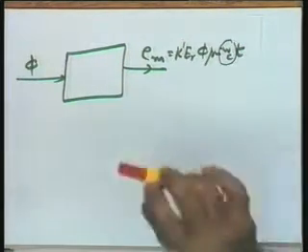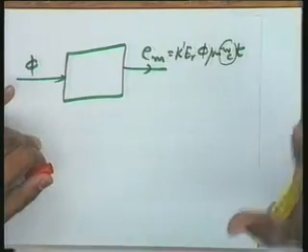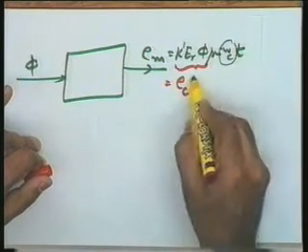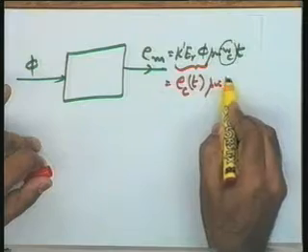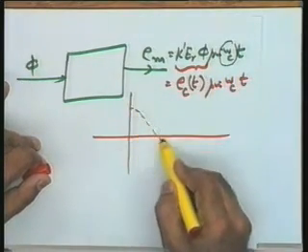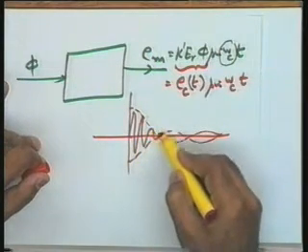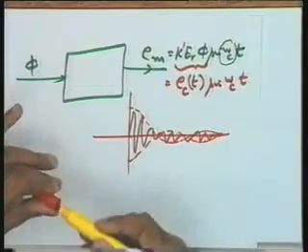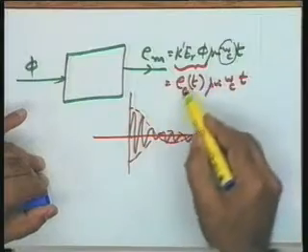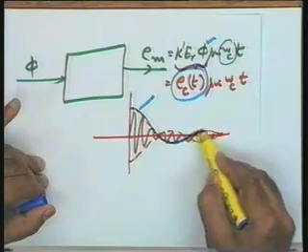Since it is the operational frequency of the device, it really does not carry any information about the error of the system. For example, if I take this total quantity as Ec(t), then Ec(t) sin omega_c t is Em. What is the nature of this signal? A typical signal is going to be like this. This is the output of the synchro error detector. Actually the error phi is given by Ec(t), which is nothing but the envelope of this particular signal.